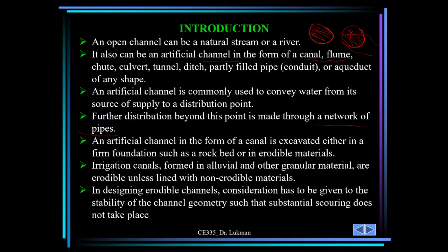Our channels can be lined or unlined. We usually line with concrete. We line our channel with concrete. Lining it will avoid sediment transport in the channel, because transporting sediment in our channel reduces the efficiency of the channel.